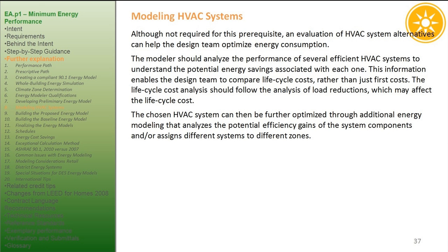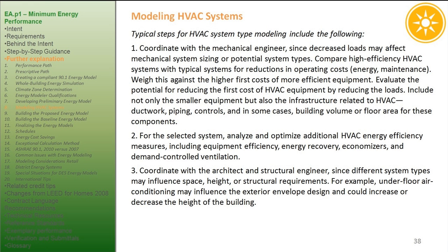The lifecycle cost analysis should follow the analysis of load reductions, which may affect the lifecycle cost. The chosen HVAC system can then be further optimized through additional energy modeling that analyzes the potential efficiency gains of the system components and/or assigns different systems to different zones. Typical steps for HVAC system type modeling include the following.